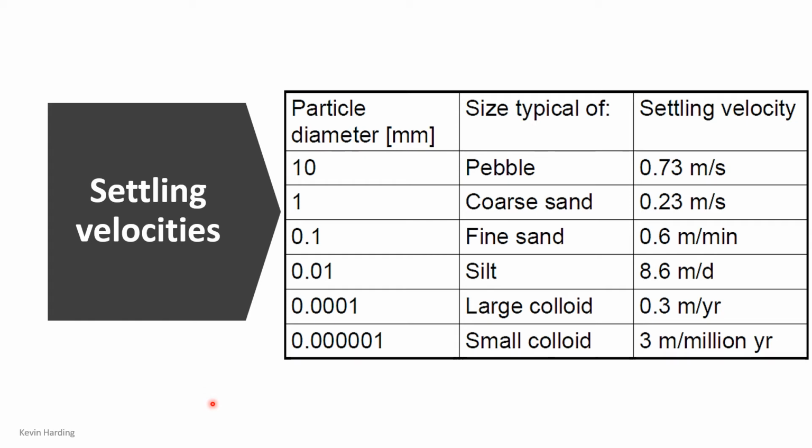It's easier to have, as we said previously, those big spaces and just have the particles settling out over days. So 8.6 days is still a fairly long time, but it probably is manageable in some of these systems. I've heard of wastewater treatment plants that typically have a residence time of about 2 weeks.